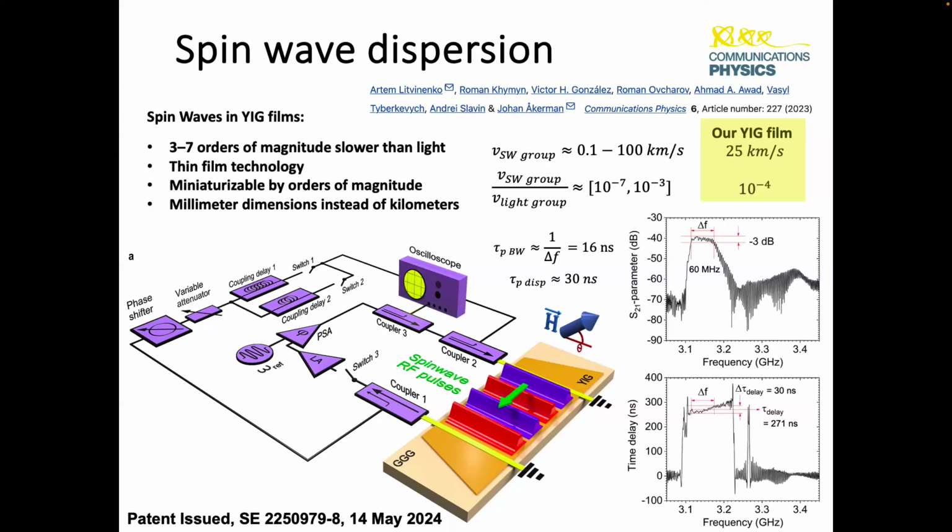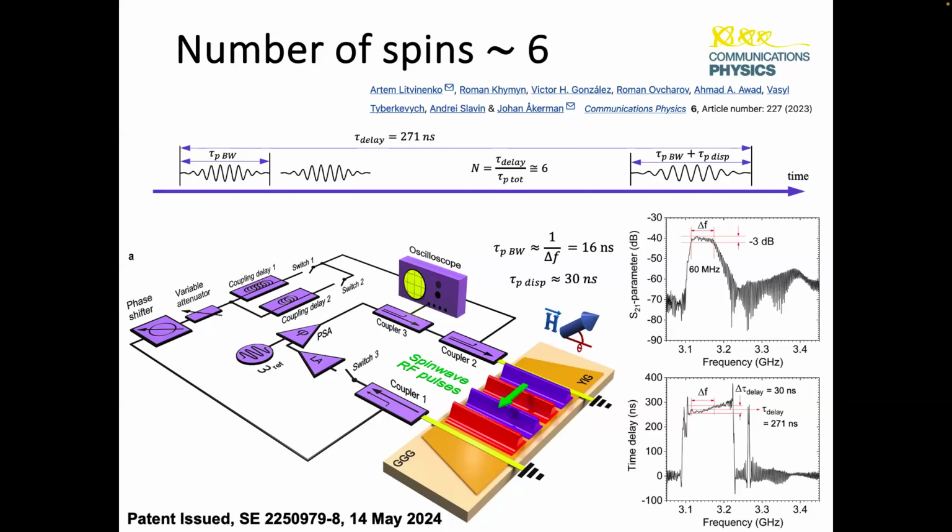are additional issues. The nonlinear dispersion will make the time delay, the speed, higher at low frequencies than at high frequencies. So the time delay will be longer for the higher frequency ones than the lower ones, and that leads to spreading of the pulses. So if we add that together, we're going to start with some bandwidth limited pulse length, and then we're going to end up with a bandwidth plus dispersion limited pulse length here, when we have to fit those into the waveguide, and that's what we end up with.